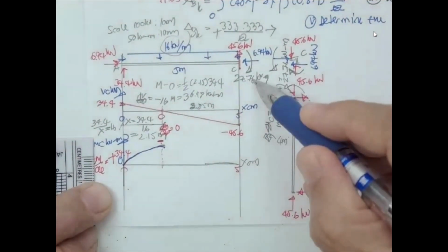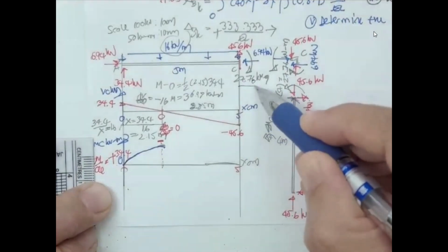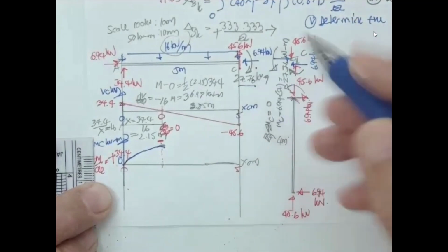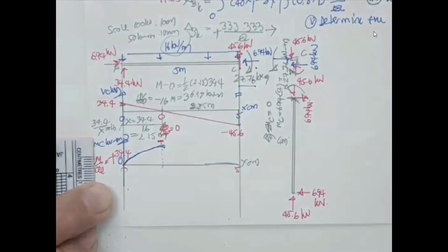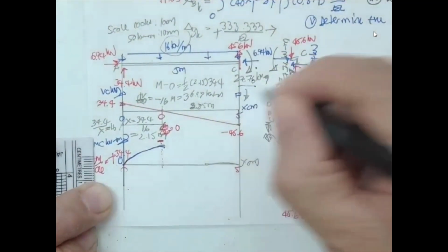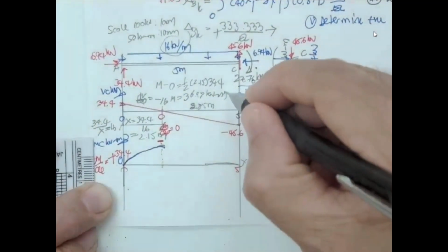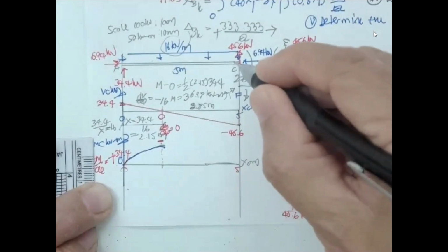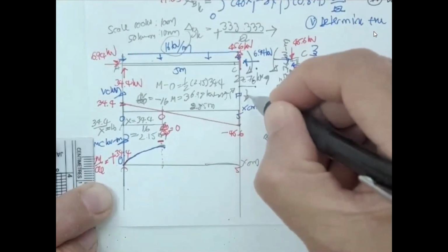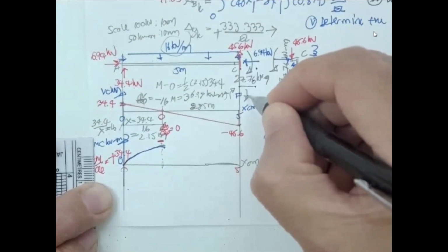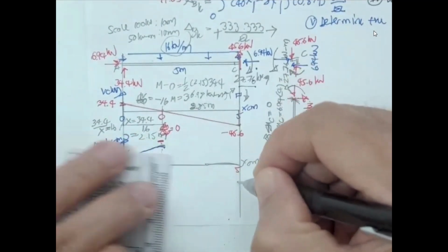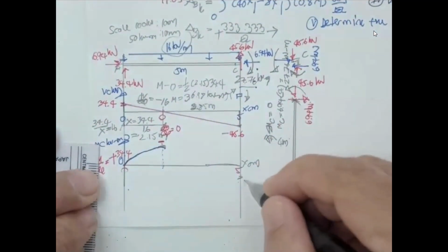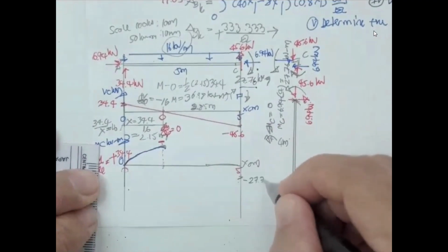And you know the moment over here, 27.76. Is this positive or negative? You may cut it over here. Okay. And then with the positive sign convention, you have moment M about this point plus 27.76 equal to 0. So this is going to be negative, nearly 5 point something millimeter, minus 27.76.